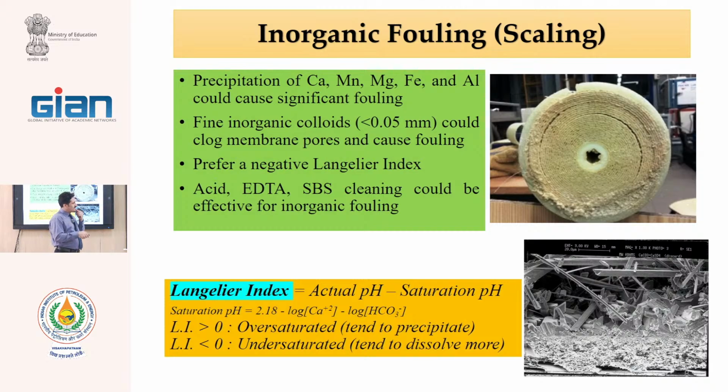EDTA can complex with metals and produce a soluble complex. Therefore, with the use of EDTA in a cleaning agent, we can rapidly dissolve these deposits. And other cleaning methods I will discuss in the last slides.